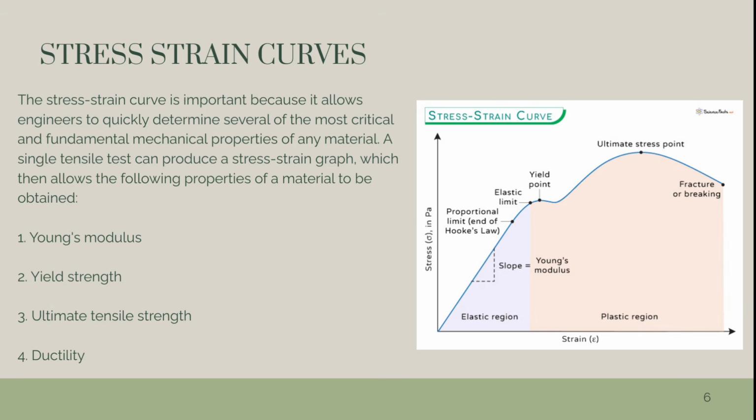There are several stages showing different behavior, which suggest different mechanical properties. To clarify, a metal can miss one or more stages. The linear portion of the curve is the elastic region, and the slope of the region is the modulus of elasticity, or Young's modulus. Plastic flow initiates at the upper yield point and continues at the lower yield point.